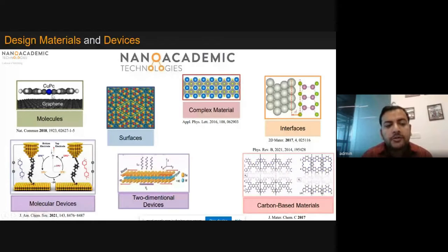With the molecular builder, molecule based devices are possible, where if you build the molecule and want to connect it with a metallic electrode, you can connect the molecule with the electrode. As you can see, the bottom or top electrode you can specify, and that can form the device applications. You can make surfaces also. If you want to define some plane, such as the 100 plane, 001 plane, 111 plane, or other Miller indices, or create some vacuum in your lattice, you can define that surface structure in particular planes.